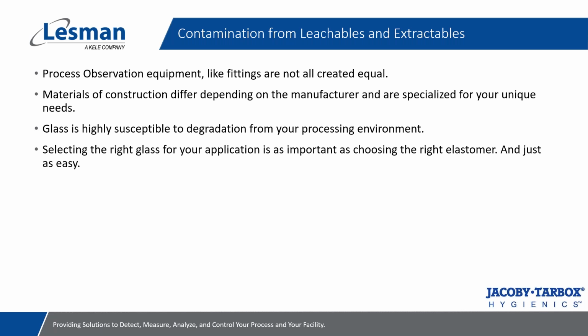I think the comment on the rupture disc. Mm-hmm. Is there a pressure or vacuum limit for your clamps? It's a question of application. Yeah. So, all of our clamps have pressure ratings just like everybody else's on the market. I believe, starting off with our lower size clamps, generally the pressures degrade as you get up into larger nominal sizes. Our 1/2, 3/4, and inch and a half clamps, and I think even up to our 2-inch, are all rated for 50 bar, which is like 725 PSI. In most cases, your processes won't even be able to generate that much pressure.